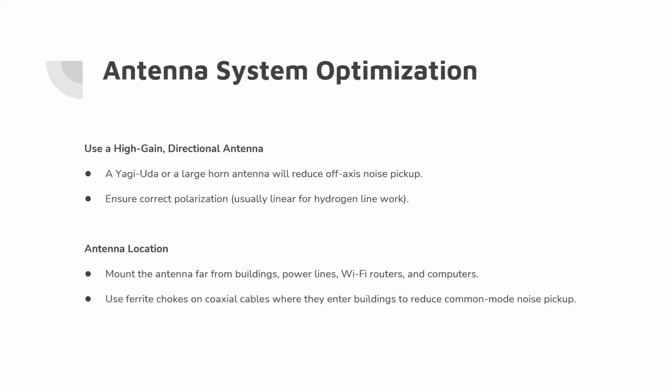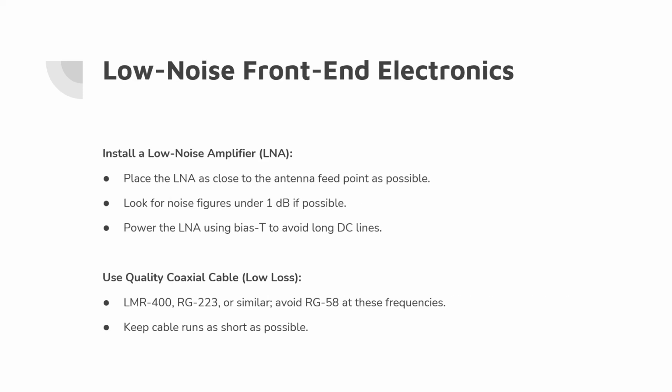So that's the only advantage I would think would be provided by trying to use a given polarization: to reduce somewhat the ground effect of RFI by using the vertical polarization rather than the horizontal, where you're picking up more of essentially the horizon. So trying to go with a vertical polarization would be what I would suggest. And since it doesn't matter for hydrogen, it shouldn't make any difference on the hydrogen signal itself.